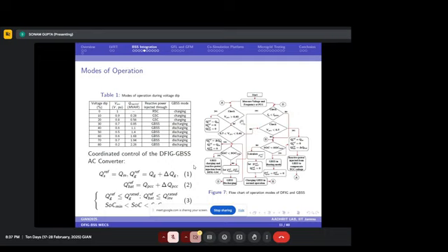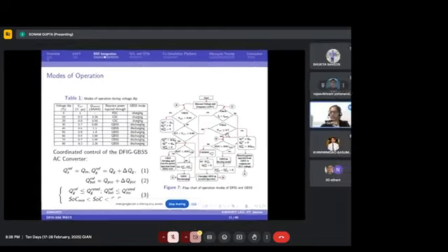according to these requirements or conditions, and the grid frequency is less than the grid minimum frequency. So what is happening here is only the DFIG comes into action, only the rotor side converter and the grid side converter as well, both are coming into action for the reactive power maintenance. But once the voltage at the PCC will be less than 70%.